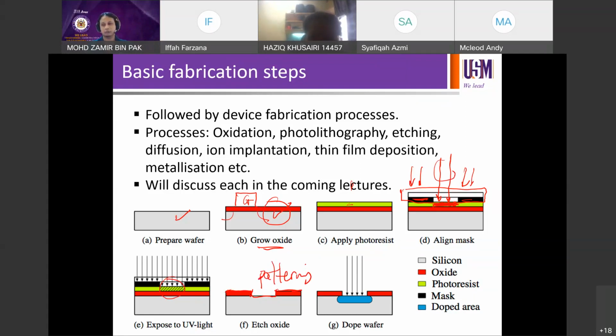So in terms of circuitry, later on you're going to have circuit at some point in some areas and no circuit in some other areas. So it's called patterning. We pattern it. And then the moment it's open and exposed, you can actually do the doping process. This area is no longer covered by the mask or resist. So you can then send your dopant such as boron or phosphorus into this exposed area to do the doping for P-type, N-type, P+, N+, P++, depending on the design.